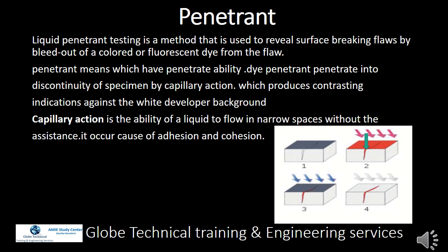Penetrant means a liquid which has penetratability. Dye penetrant penetrates into discontinuities of the specimen by capillary action, which produces contrasting indications against the white developer background. Capillary action is the ability of a liquid to flow in narrow spaces without the assistance of external forces. It occurs because of adhesion and cohesion.